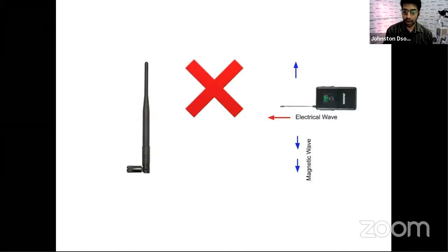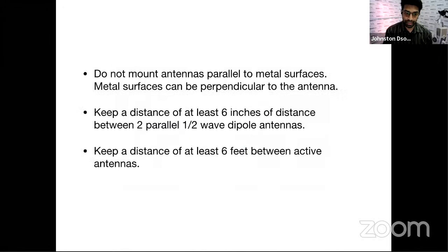So when you're putting any powerful antennas, any antennas that are amplified, you make sure that the antennas are at least 5 to 6 feet away from each other, because they're powerful. The power is amplified. They have a lot of forward gain. So if they come close to each other, you'll start getting problems in both the signals, whatever you're sending.